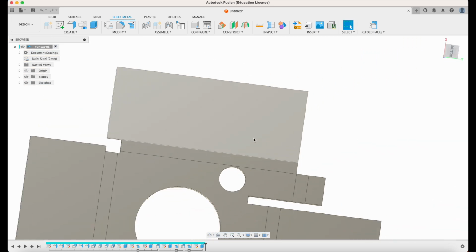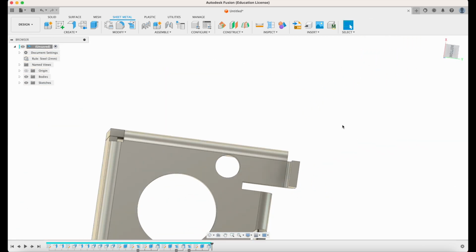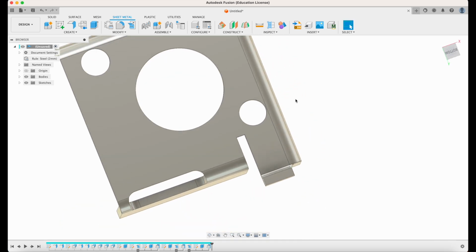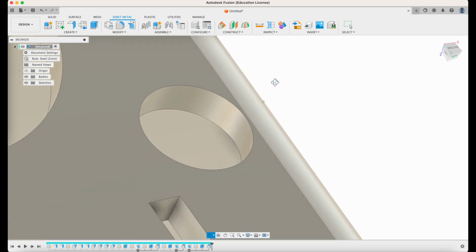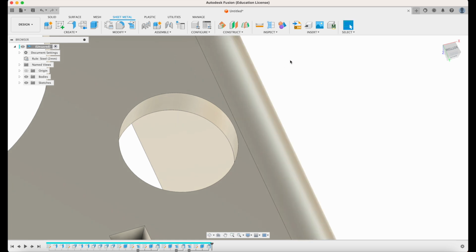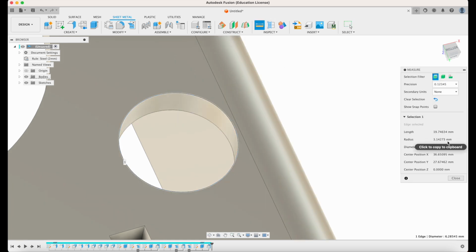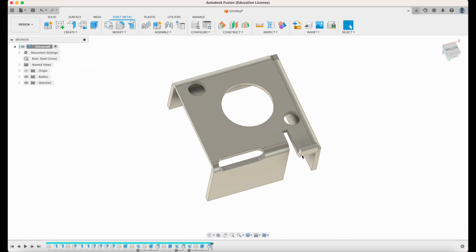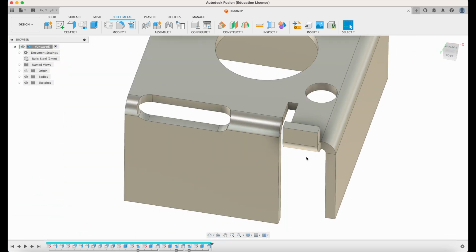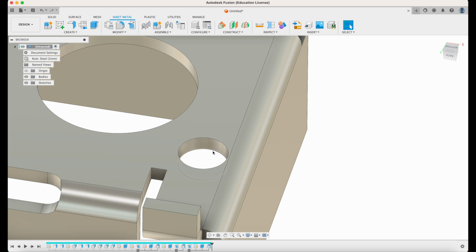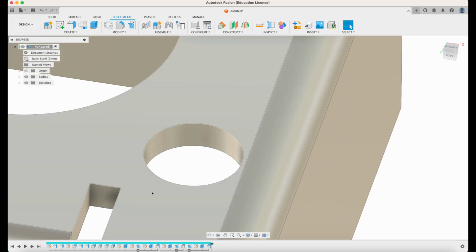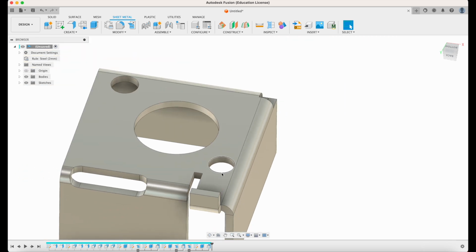Okay, and refold. Okay, Fusion is still showing a perfect circle. And if we take our measure tool and measure it, you can get a radius, which means the circle is still a circle for Fusion. Now, this is a problem. This is where Fusion lacks the ability to show the deformation of this hole that will happen in real life.